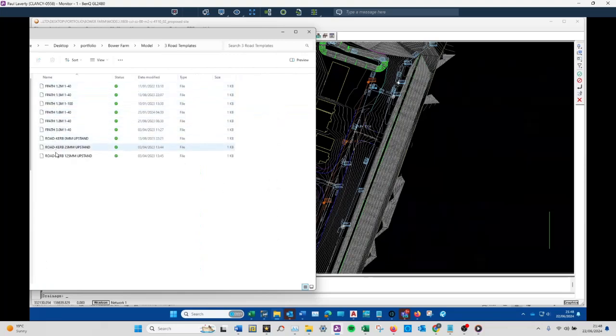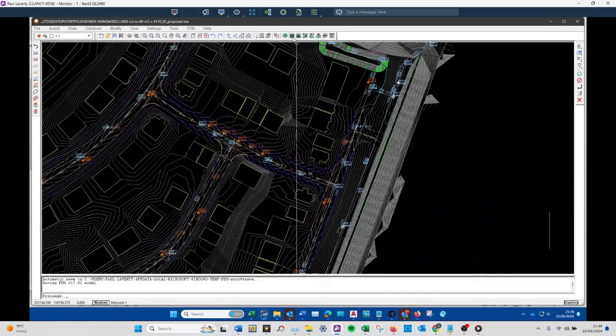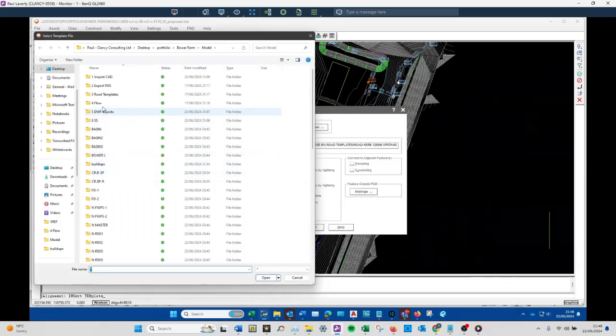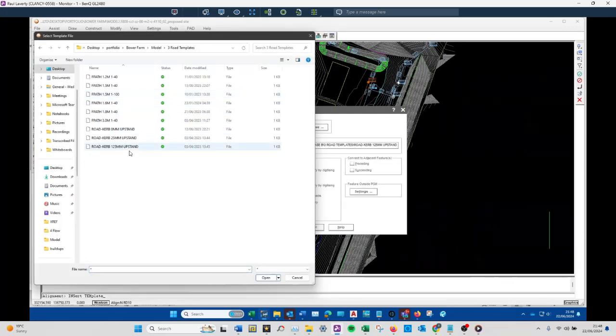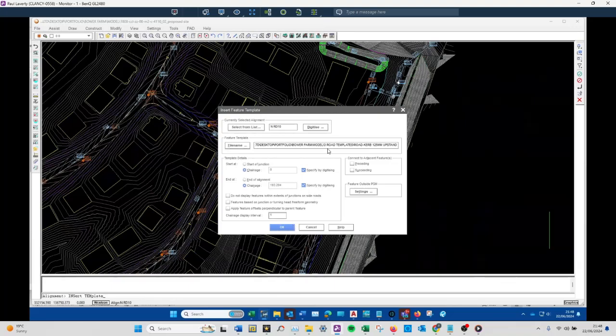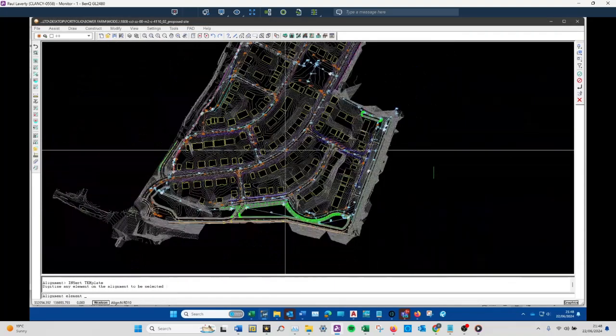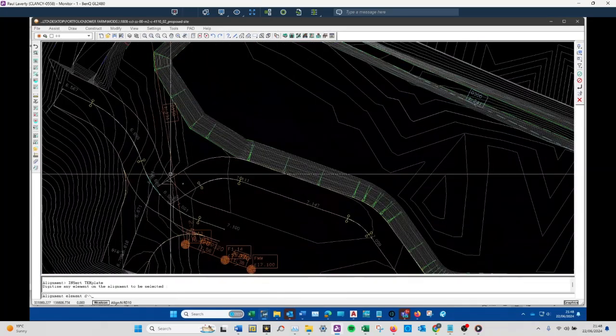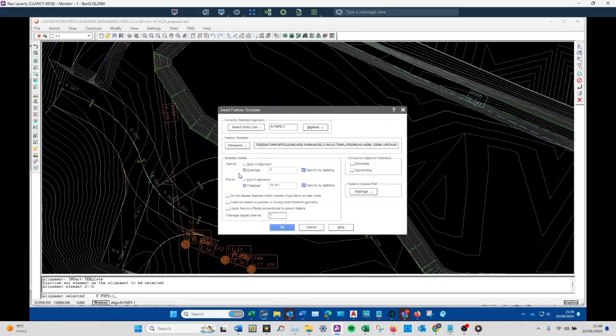When you do a road design, you are adding the curbs, you're adding footpaths, you're adding verges, you're adding all kinds of stuff to that road. The idea is that you put a curb line that's attached to your road, or a footpath that's attached to the road, so that as the road design changes, maybe you change the camber, maybe you change the vertical alignment, or maybe even you have to change the horizontal path of it because the swept path doesn't quite work.